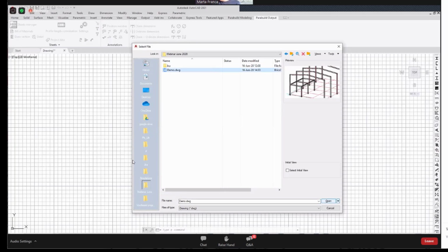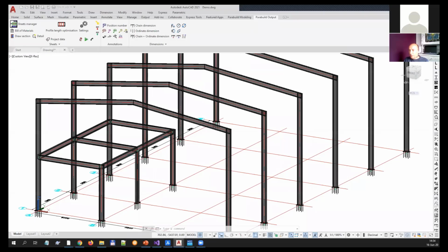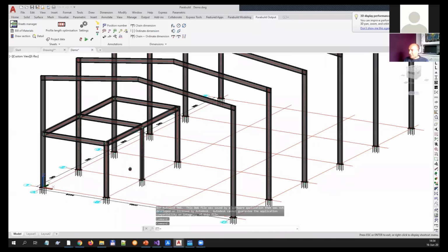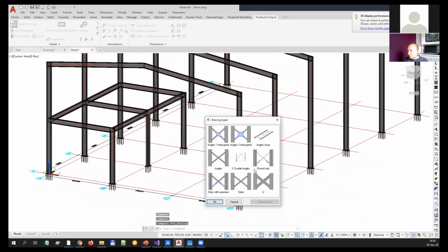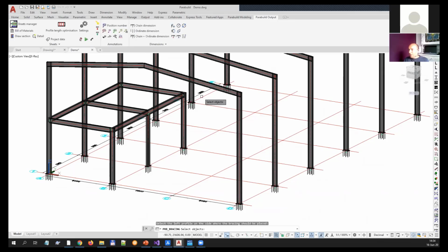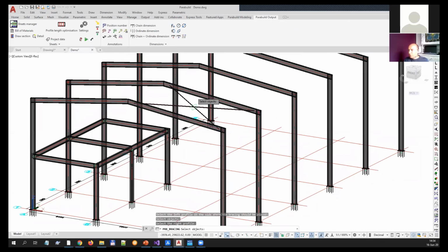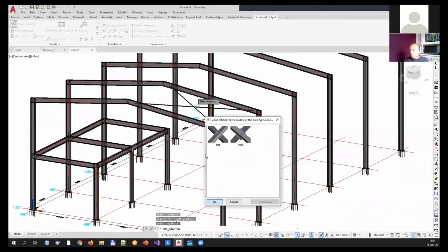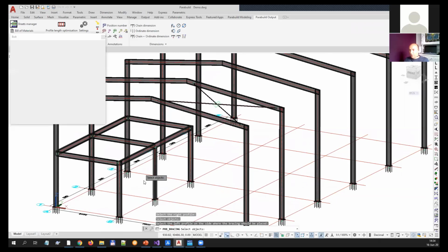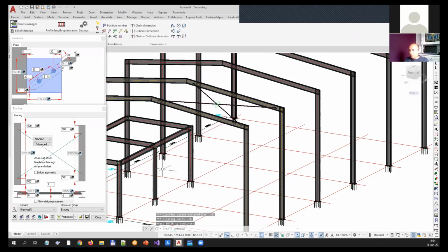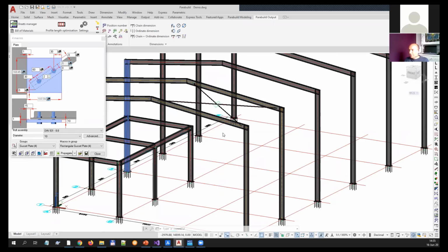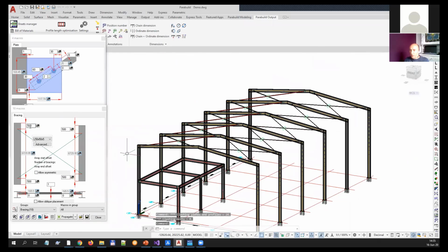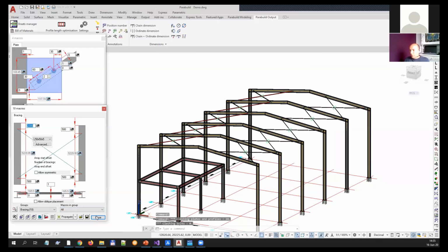And you will see that when I continue working on the same drawing here. Okay, so the next thing I'd like to show you is bracings. Angle bracings. I'd like to add them here in the roof. The bracing command is really just a command that helps you insert several macros at the same time without having to do all the manual clicking. So that's why it's asking for the gusset plates after drawing the cross. So this is the bracing macro. I can just propagate that, and that should propagate it to all the other rafters, and I could do a change. So that's just an example.